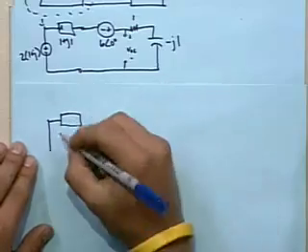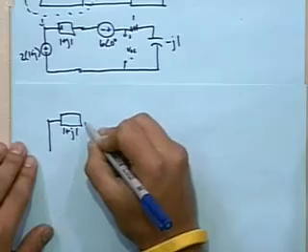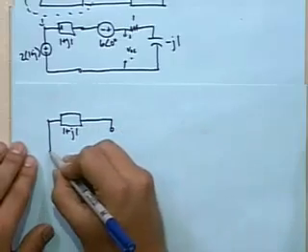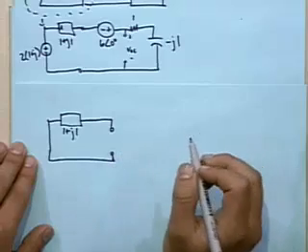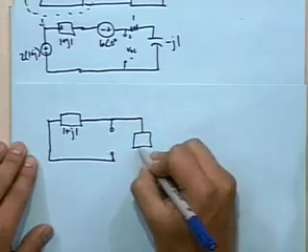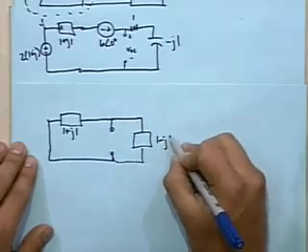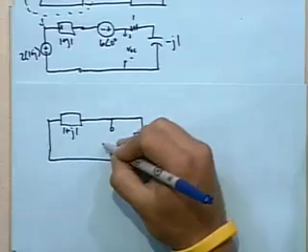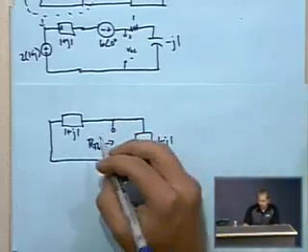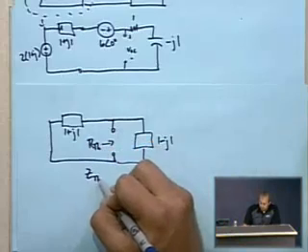We have this 1 plus J1 impedance, that voltage source gets shorted. Here's one terminal of our load, and then we've got the other impedance over here, which we can characterize as 1 minus J1. And so that's where we're looking to find our Thevenin impedance, and I guess rather than calling it R Thevenin, it should really be Z Thevenin.